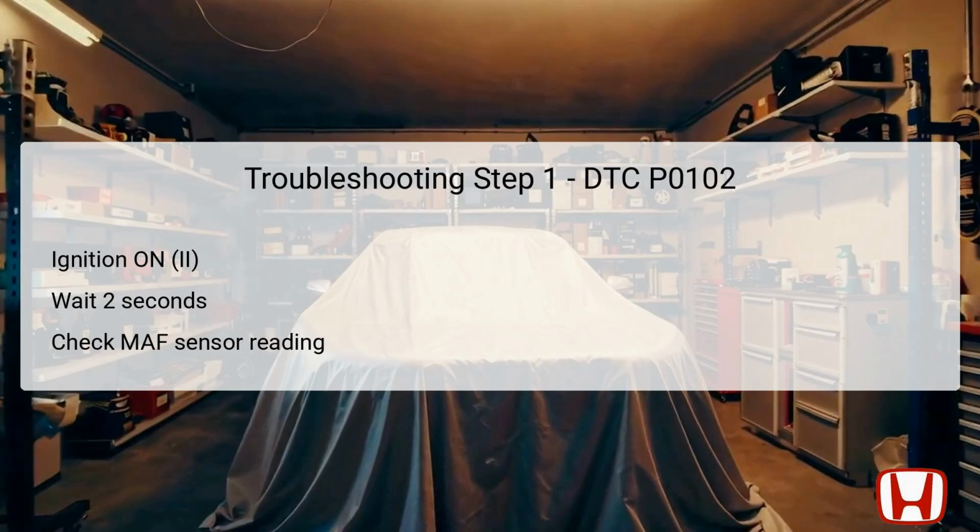Following this, check the reading of the MAF sensor using the Honda Diagnostic System HDS data list. If the reading indicates approximately 0 grams per second, g/s, or shows a voltage of 0.1 volts or less, this confirms a potential fault with the MAF sensor or its circuit.